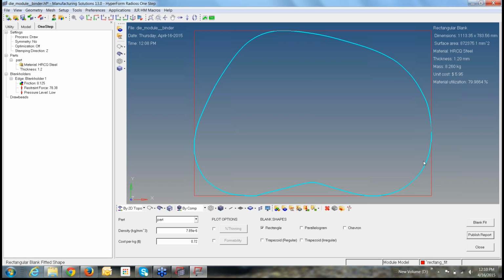the flattened blank shape. In your forming stages or incremental forming, you can use either you can create a surface out of your rectangle, or you can use this odd flat blank shape to set it up as incremental forming. This can be a starting point for your incremental forming.